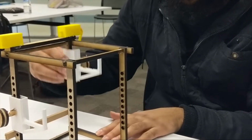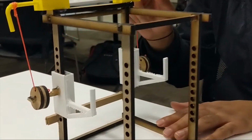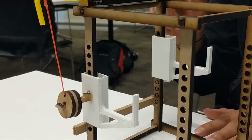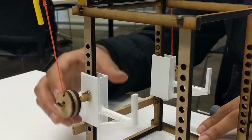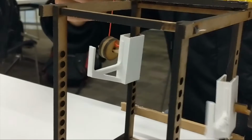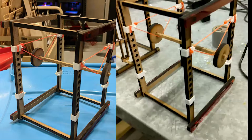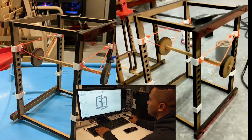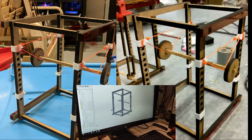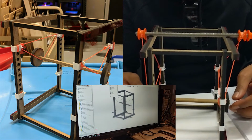The model shown resembles this combination, where 2 arm features shown in white shadow the barbell, allowing the user to experience 2 degrees of freedom, hence maneuverability or comfortability during an exercise. Sensors will track the position of the bar and inform 2 independently driven motors to reel up the arm parts when required. For this prototype, the concept uses pulley and belt mechanism to control and operate as a safety tool, which enables the user to freely move around the bar in any direction with only constraints of 2 belts holding it on each side that won't pull the bar unless user fails from holding the bar.